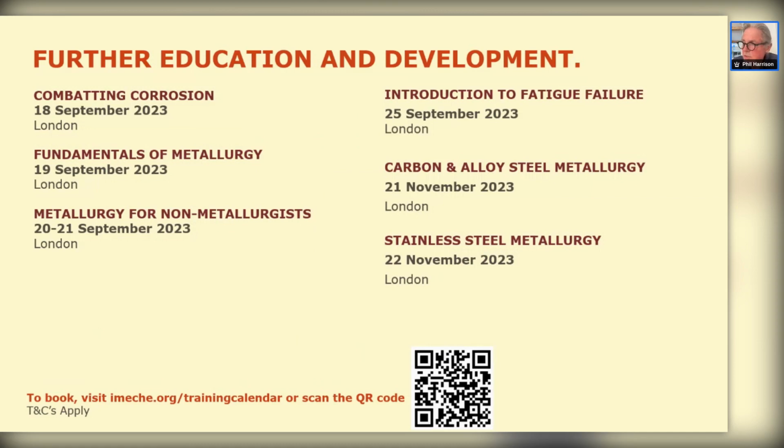But on metals, to me, there are still too many inherent problems with the process. For example, oxidation, porosity, can we guarantee strength, and so on. It might go down the route where we do it like we do with castings, where something is made and then the 3D printing does several test pieces. And we assume that if the test pieces pass, the material's adequate for use, as we do with casting. So I don't know, that might be the way things go in the future.